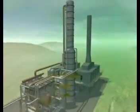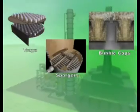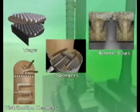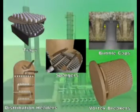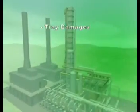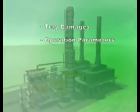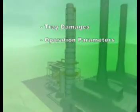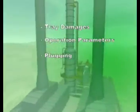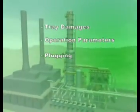We looked at various internals like the trays, bubble caps, spargers, distribution headers, and vortex breakers. Other subjects covered include causes of tray damages and the results thereof, the effect of changing the operation parameters like reboiler temperature and draw rate, causes of plug trays and distribution headers and their symptoms.